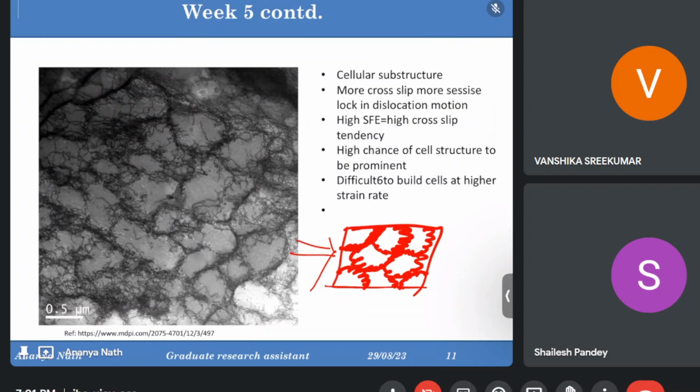If we increase the temperature, obviously this will happen more easily and faster. Pile up of dislocations happens at the grain boundaries, because those are the places of highest energy gradient, and all the fracture and piling up happen at the grain boundaries only.